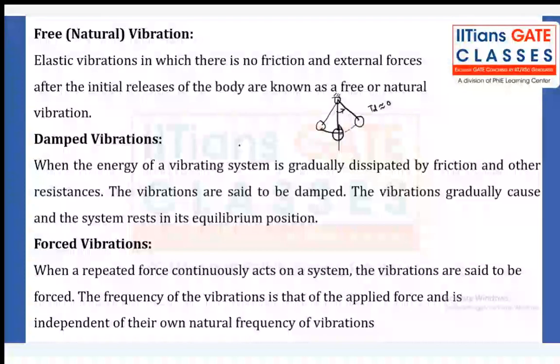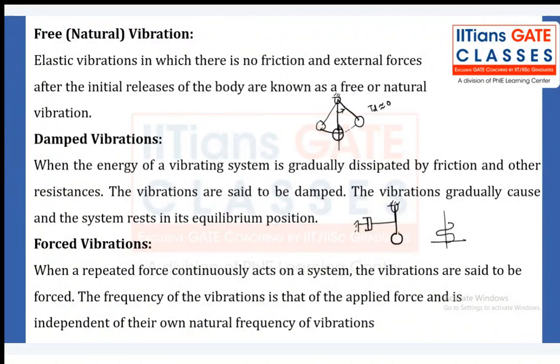Damped vibration, same thing, but the extra thing is a damper. A damper will also be present in the system like this. Now there is a damper in the system. When there is a damper in the system, my friend, what will happen, guys? Whatever the oscillation that was continuously happening with the same magnitude, now because the damper is nothing but friction, fluid friction, that oscillation will die out after some point of time like this. Exponentially, this particular oscillation will die out. Those types of vibration will be called damped vibrations.